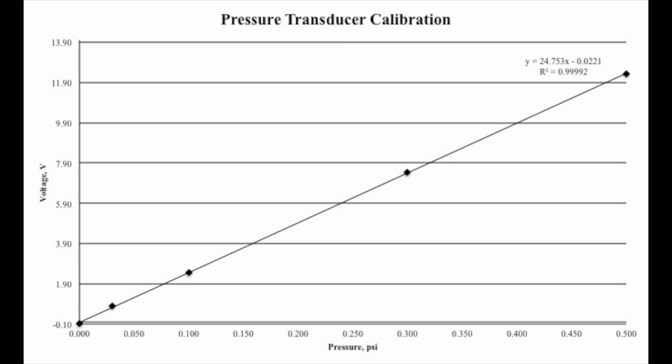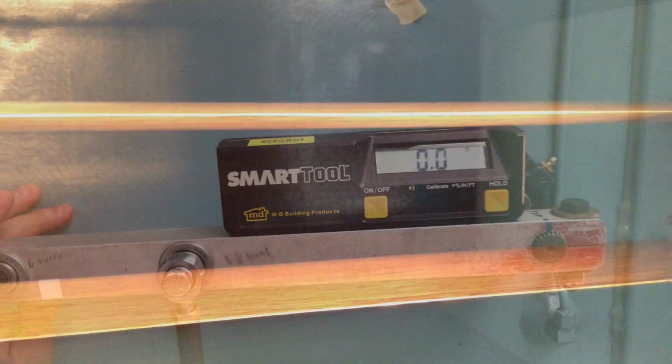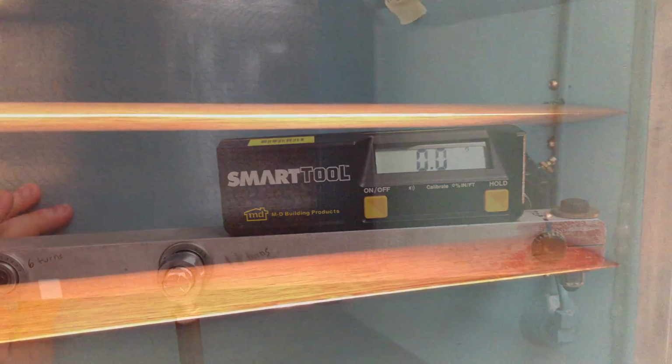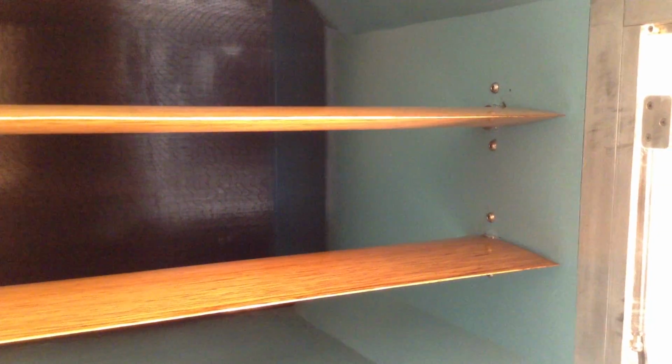The last verification is to check if the angles of the vanes are at 0 degrees prior to the start of the test. This ensures correct free stream velocity. For our system, this is done by measuring the height of the trailing edge relative to the base of the test section of the low-speed wind tunnel.